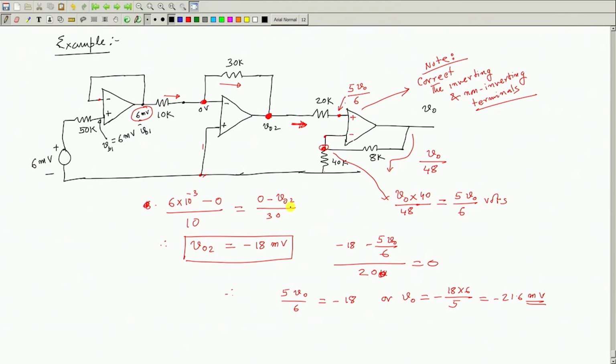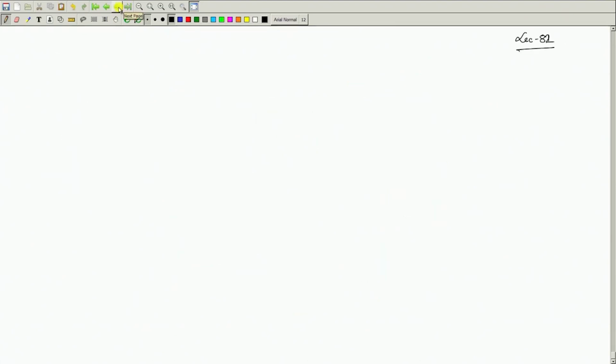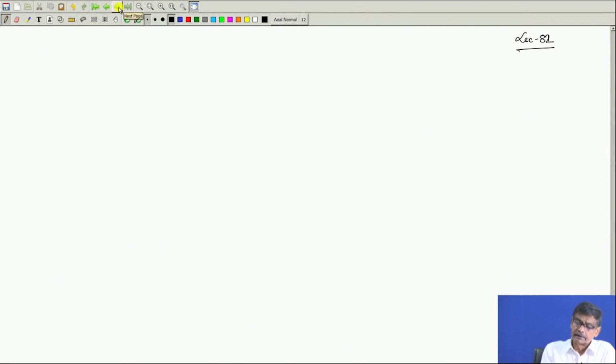So, this rule, that the voltage of this point and this point are the same, is true if there is a negative feedback with a passive element like some resistors, inductors, capacitors, whatever it is, and there must be negative feedback. And today I will first tell you about one interesting circuit based on op amp, which will do some general impedance transformation.